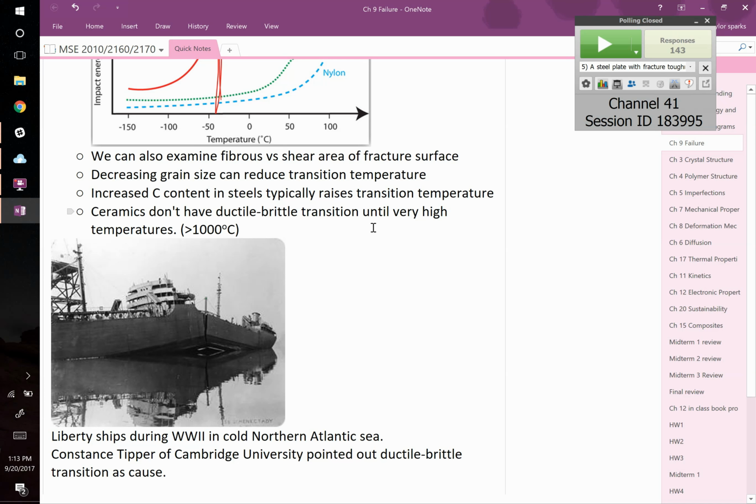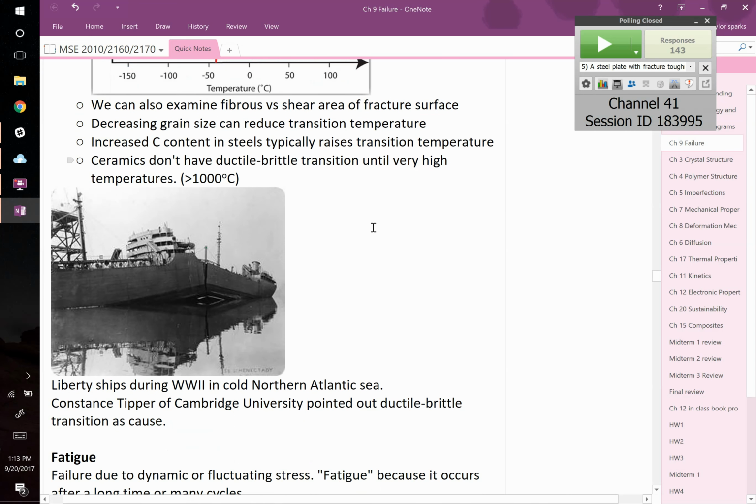Some people thought this is why the Titanic sunk. They said, oh, is it way up north where it's brittle? It hit an iceberg, and instead of just denting, it actually just fractured, and that's why it went wrong. There have now been really clever material science studies that actually looked at the rivets, and it was actually really poor quality rivets that they used that actually sheared, and then plates actually probably just fell off. So it probably wasn't a ductile to brittle transition failure there, but it definitely was with the Liberty ships in World War II. So this is a big deal.